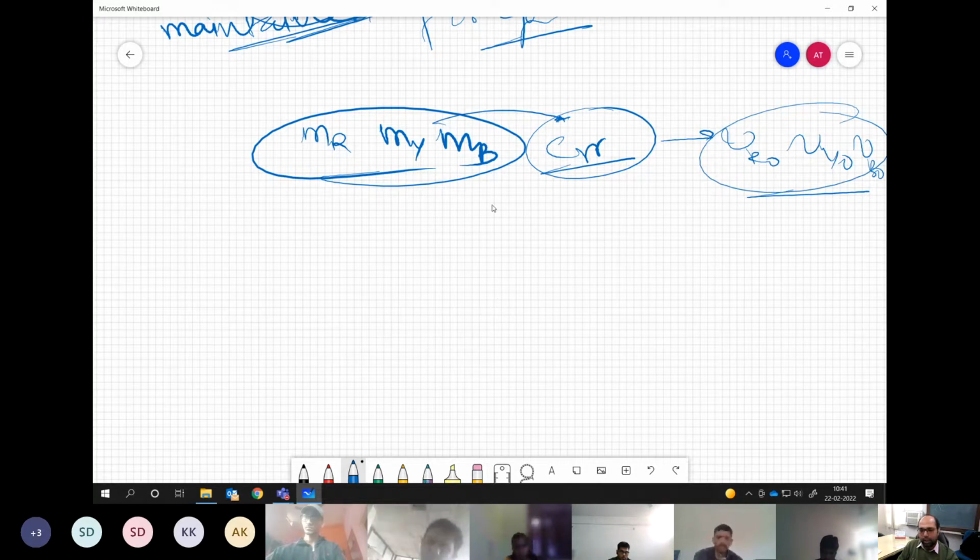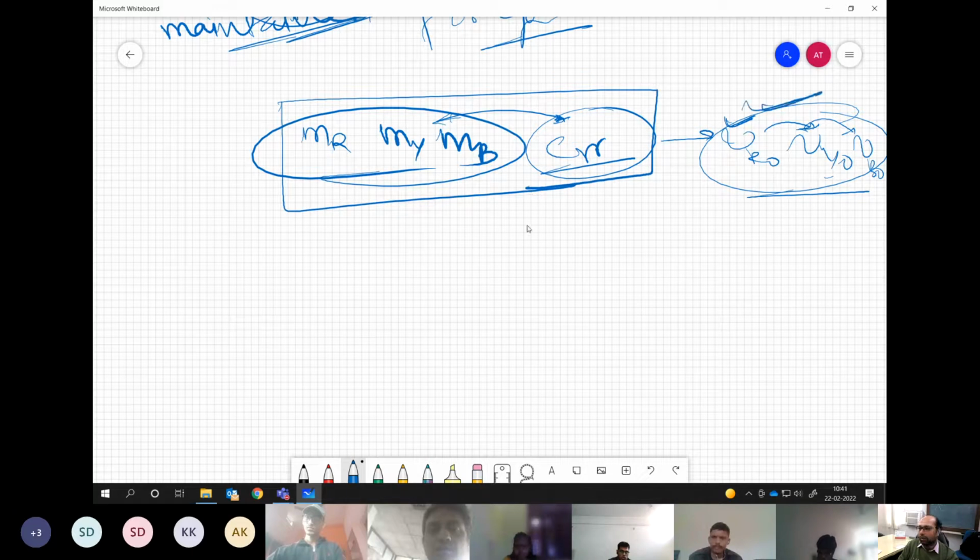Understanding my point? So there is no way that we can force that, okay, if we have generated VRO, we will shift it by 120 and generate VYO. Or we will shift this VYO by 120 and generate VBO. No, we cannot say that. This is now out of control for us. So we should have a mechanism here itself to maintain this three-phase symmetry at least.